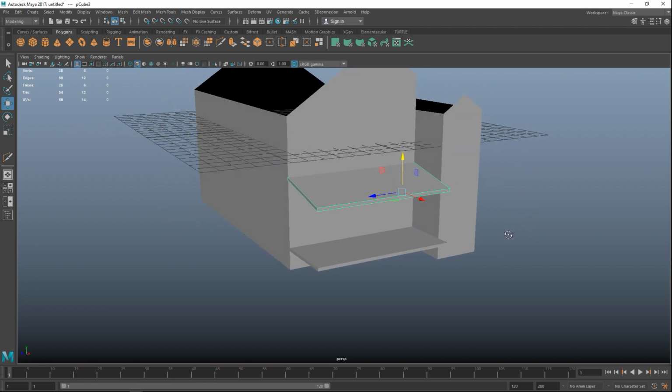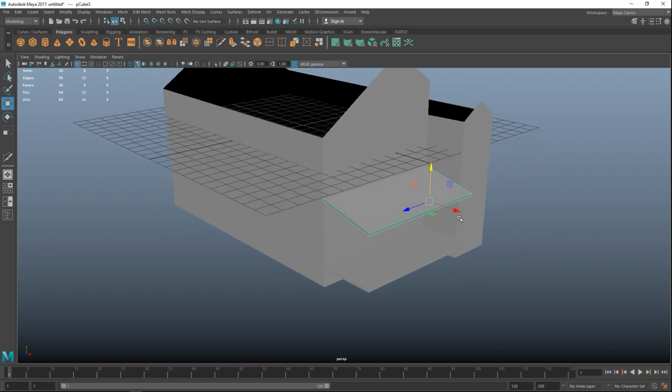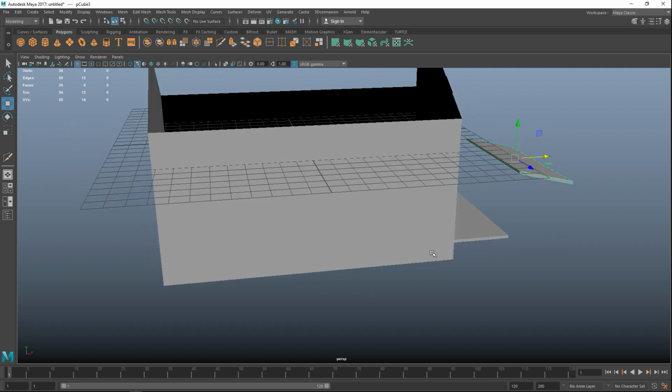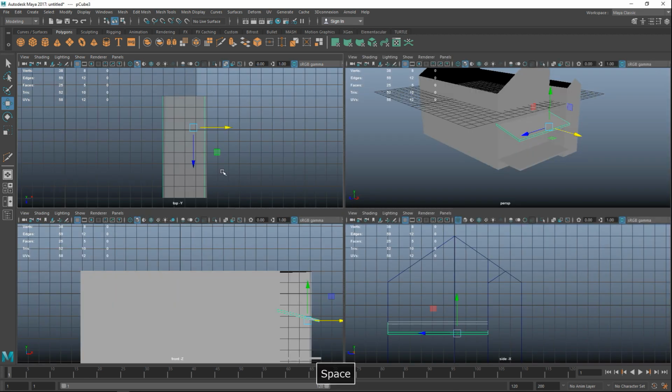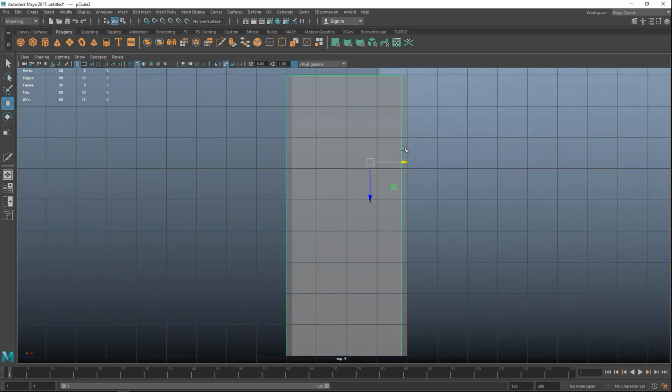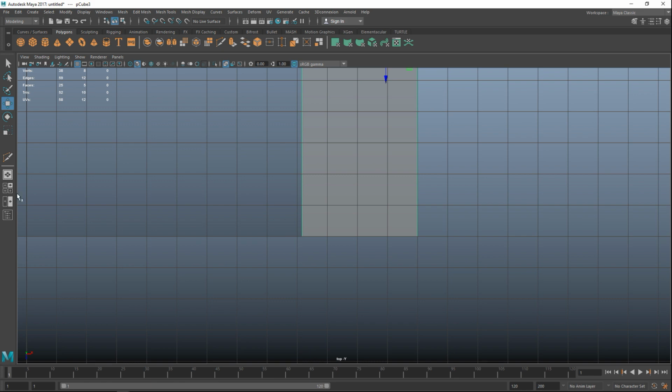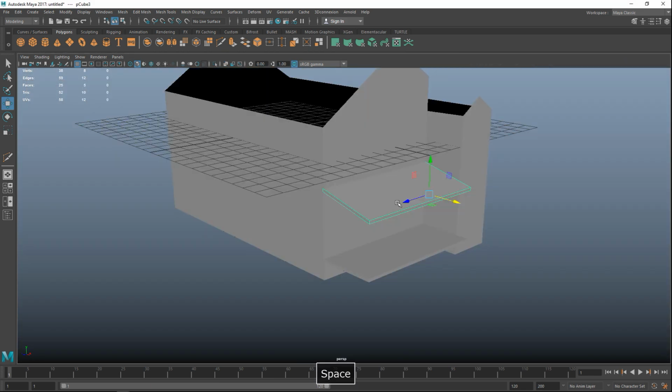So let's start with our first vertical pillar. And actually, before we do that, we're going to pull this out a little bit. And let's right click on the face, select that back face and delete that. For the simple fact that it's additional poly count that we don't need. Okay. Just going to go in here, F to zoom in, make sure I got a clean connection. And we're good. All right.